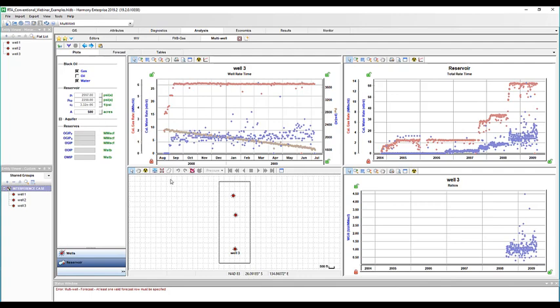There's a couple of ways you can do that. You can simply type in your drainage area here to 636 acres, or you can actually change the reservoir boundary, or the shape of the reservoir boundary, yourself manually to increase or decrease that drainage area. So if you see, as I'm changing the reservoir boundary, the value of my drainage area on the left-hand side will actually be changing. Now, another option that you have is to bring in a shapefile. And when you bring in a shapefile, you can then match the reservoir boundaries to the shapefile so that you get a more accurate drainage area.